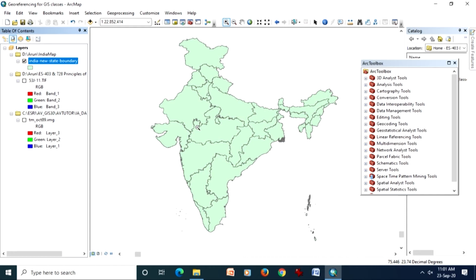That means I do not have to change anything; automatically, seeing the file which is first in my project, the next input file will follow the projection system of the already existing file, and this is called on-the-fly projection. So this will help speed up our georeferencing as well. And for those files that are georeferenced or have different map projections, the software will take care of this. These on-the-fly projection facilities are now available in many software packages also.